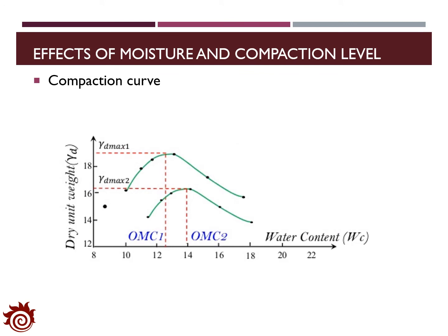The figure here demonstrates the relationship between dry density, which is a dry unit weight, and the water contents. The two lines in this figure come from two different compaction efforts. Basically, under a given compaction effort, the dry density could be maximized at one water content, and that water content is defined as OMC, that is optimal moisture content.